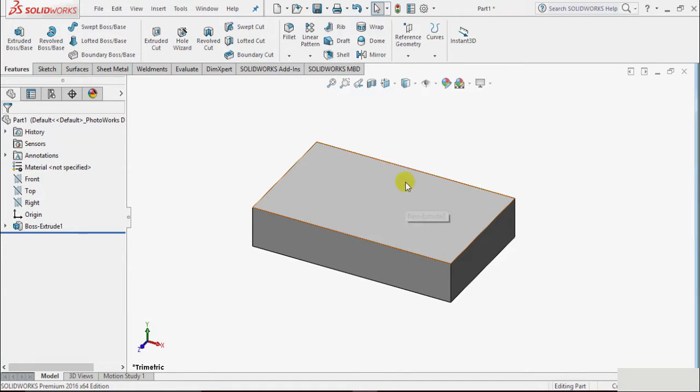And then I want to make a hole in this part. To make the hole, we have the option of hole wizard to create a standard hole, or we can remove material on any other type of profile by using the command Extrude Cut. It is highlighting that it cuts a solid part by extruding a sketch profile in one or more directions.